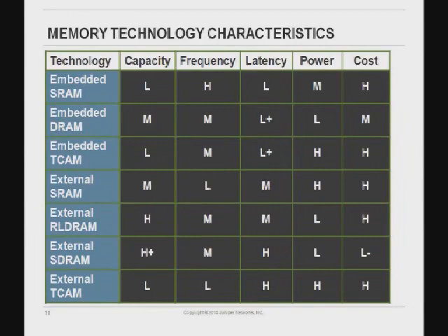So as you can see, there are a lot of choices available to us when we're trying to design a particular feature. If the memories are smaller, if you design to hold a FIB table, for example, the forwarding table, it will not give you as many entries. The scaling will be limited. And also, if you are trying to implement them on an on-chip memory, you also may face the same problem. So the scalability, the feature, and the cost at the end are very much influenced by how we put this memory in use.